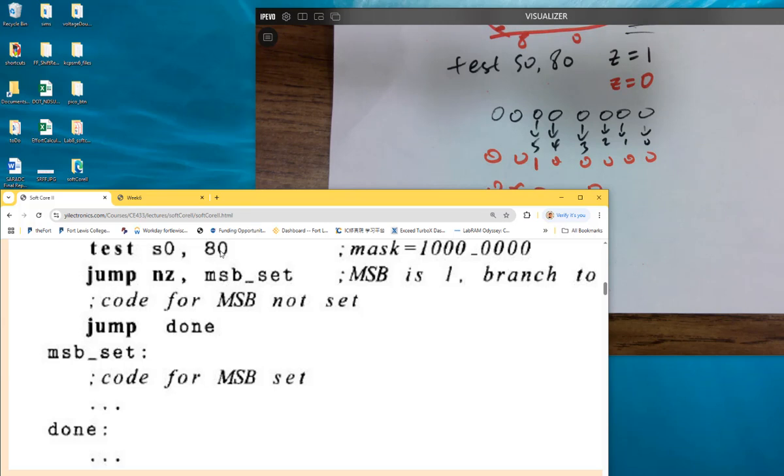Can you not put logic inside, like the other part? Like I know in AVR you could do load S2, S0 and with the mask and then you could extract it all on one line. Do you do that without doing the test thing here? What's the instruction being used for AVR? Just load. But how to load it? Just load, it's transferring, right? But how do you extract it? The assembler would kind of put it together, because if you took the original register and you anded it with the mask, it would extract it and then you load it back into it.